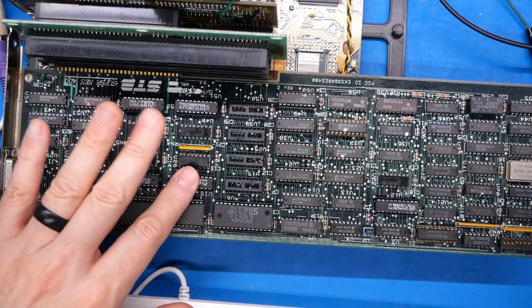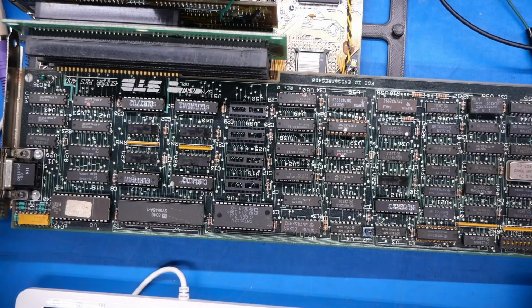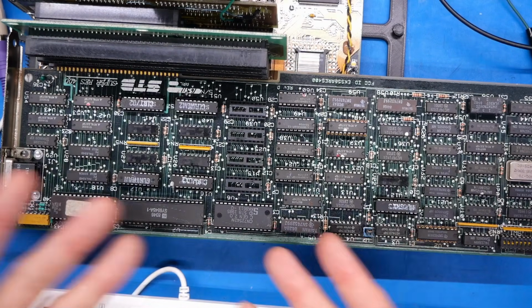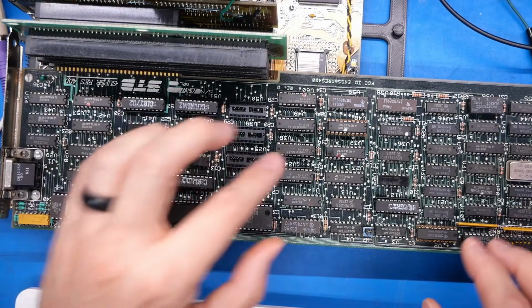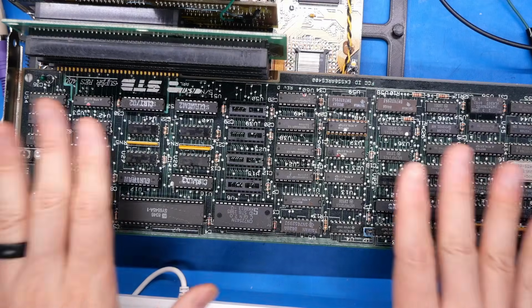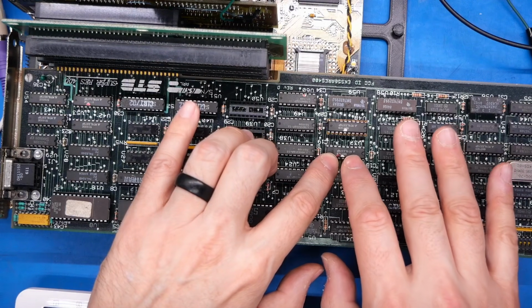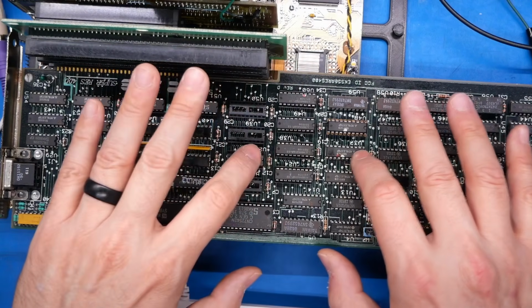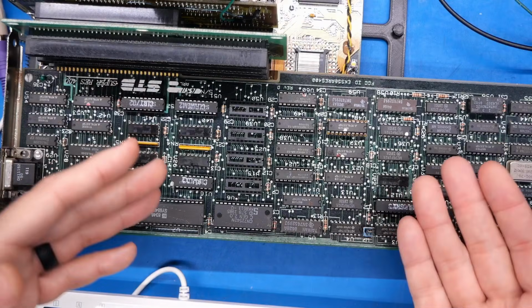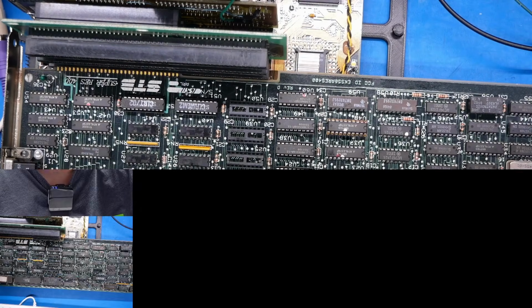Now, if this chip is the problem, by the way, I'm kind of screwed. There's no way to recover from that. This is a custom chip. It's been programmed. There's no way for me to make another one. So let's hope the issue exists over here. If when we turn this on, we see the same behavior with that weird clock signal coming out of the output of this chip, then that pretty much confirms there's a problem with this chip. I have no idea if the system's going to run with that pin out of there, but we'll see what happens. Okay, here we go.